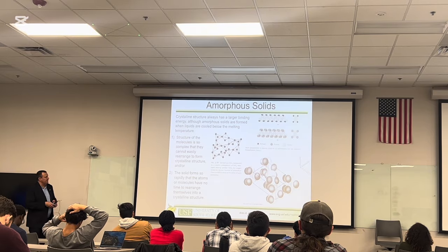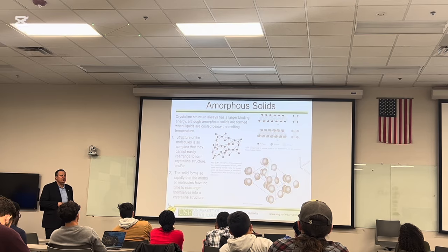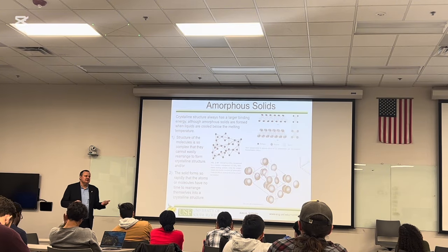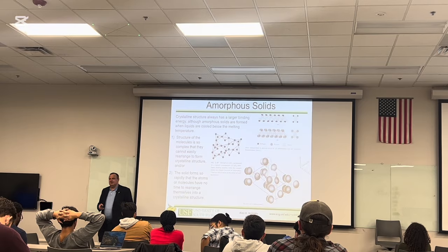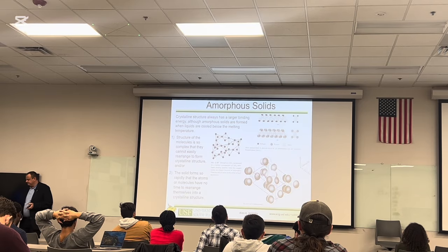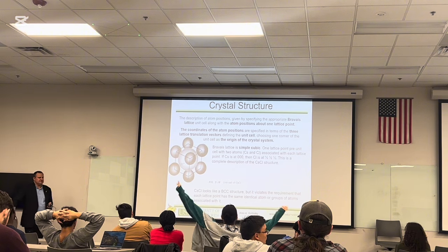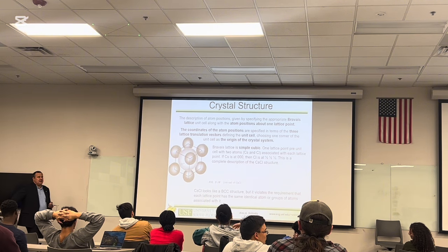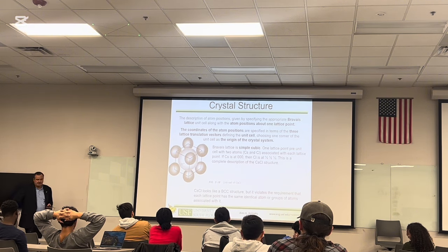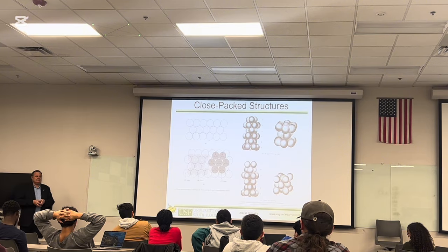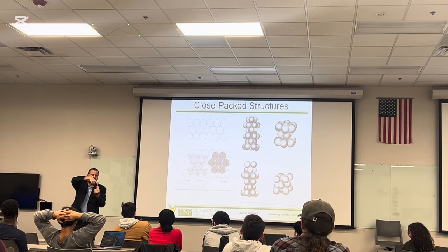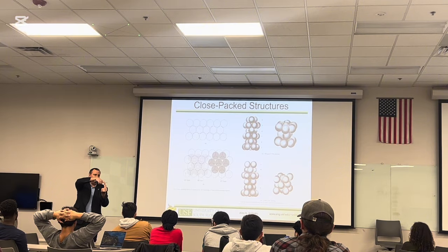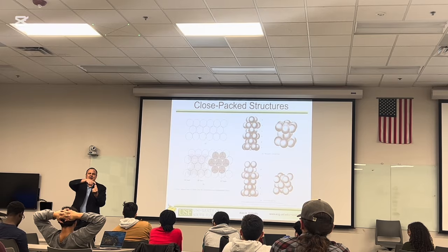And for the amorphous solids, the reason materials can be amorphous is because they were frozen very fast, or because the molecules are too long to rearrange in a periodic array, which is also possible. And then we're going to talk quite a bit about the crystal structure. The way the atoms are packed as hard spheres. And the best way to pack is take your 3 fingers together and put another finger right here. You cannot pack atoms or balls of the same size denser than this.